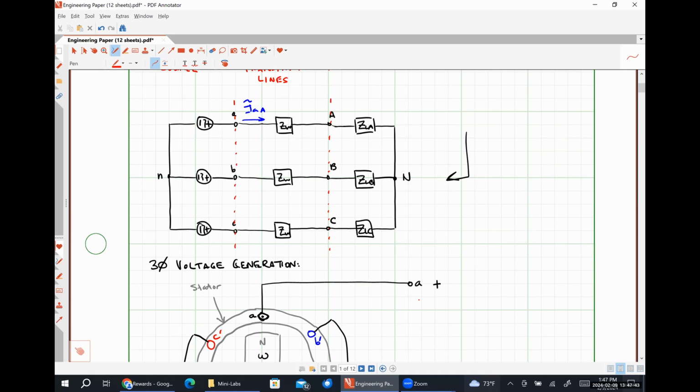If you know that you're going to have a fairly significant amount of imbalance, you probably want a neutral conductor there, because we're going to see that the neutral is actually what's going to carry the imbalance in a system. And it's going to remove some of that current carrying burden from your phase conductors. But we'll talk all about that kind of good stuff when we actually start analyzing things.